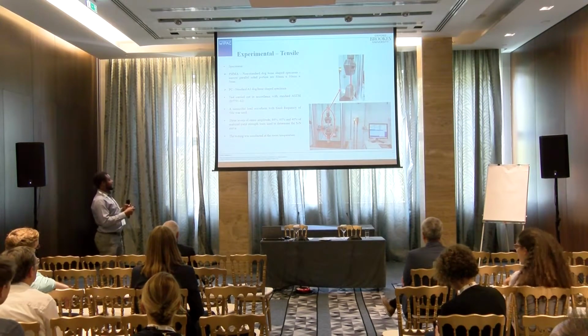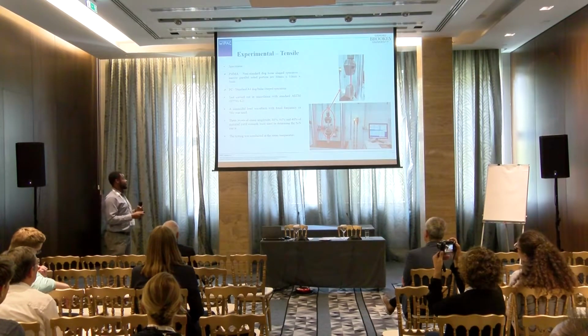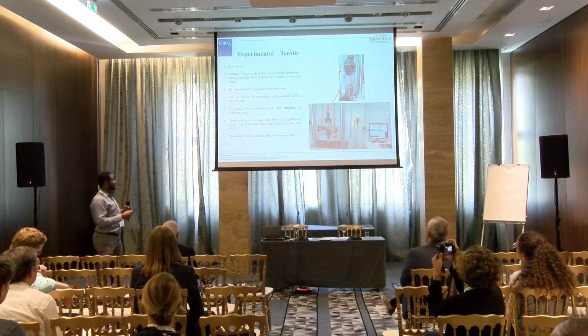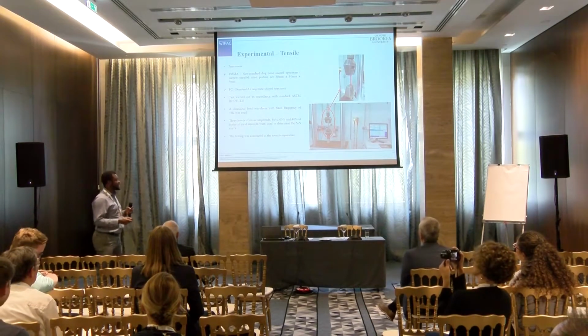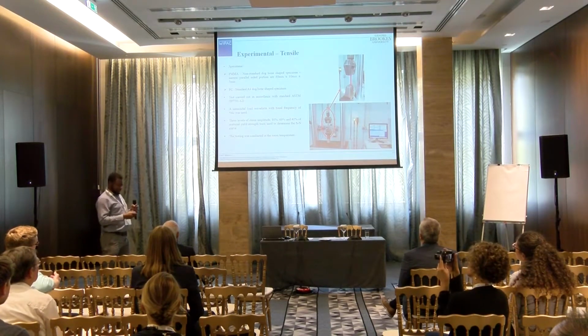The test was carried out in accordance with the ASTM standard, with a sinusoidal load waveform with a frequency of 5 Hz. The levels of stress amplitude, 80%, 60%, and 40% of material yield stress, were used to determine the S-N curve. The testing was conducted at room temperature.